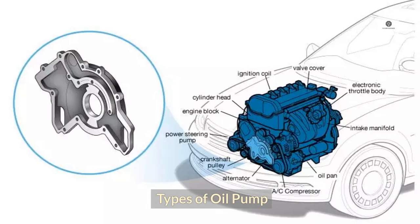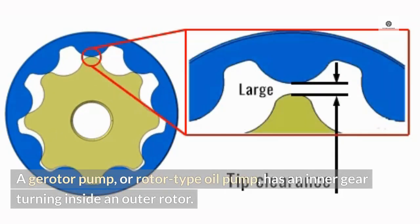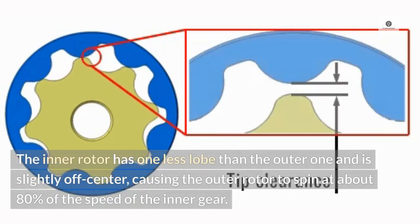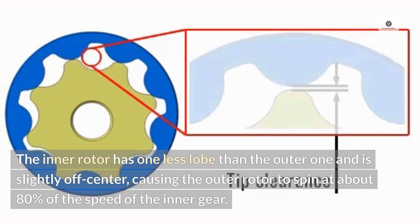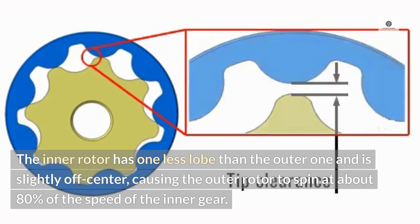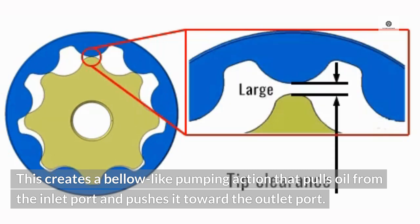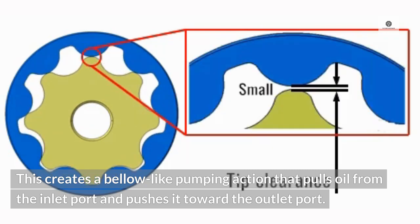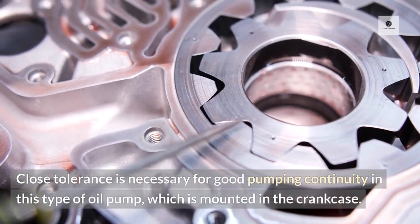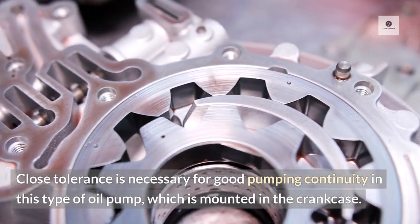Types of oil pump. Rotor oil pump. A gerotor pump or rotor-type oil pump has an inner gear turning inside an outer rotor. The inner rotor has one less lobe than the outer one and is slightly off-center, causing the outer rotor to spin at about 80% of the speed of the inner gear. This creates a bellows-like pumping action that pulls oil from the inlet port and pushes it toward the outlet port. Close tolerance is necessary for good pumping continuity in this type of oil pump, which is mounted in the crankcase.